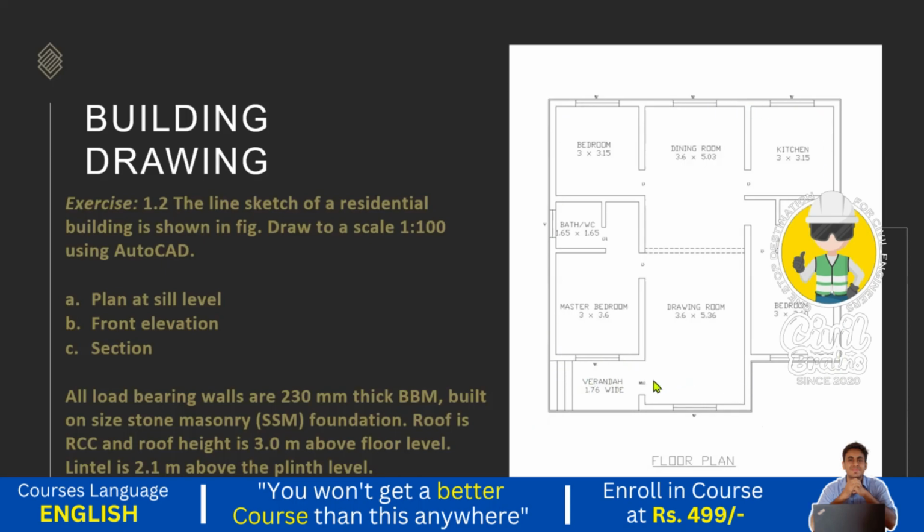Once using the offset command, next we need to draw the openings, that is all the doors and the openings wherever they are. And next, once we draw the doors and openings, the next step is we need to draw the windows. Here you can see this one. In the previous example there are no windows, here windows are there. After providing the doors, the next step is provision of the windows. Here you can see there are different windows for all the rooms. Windows are there, ventilators are there.